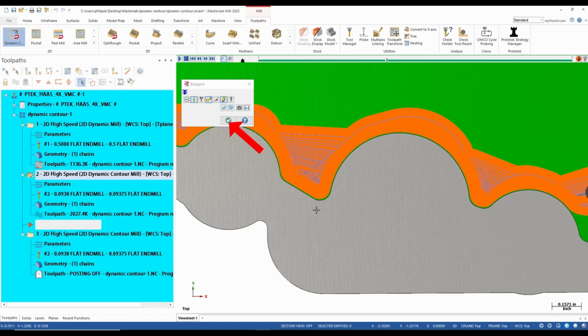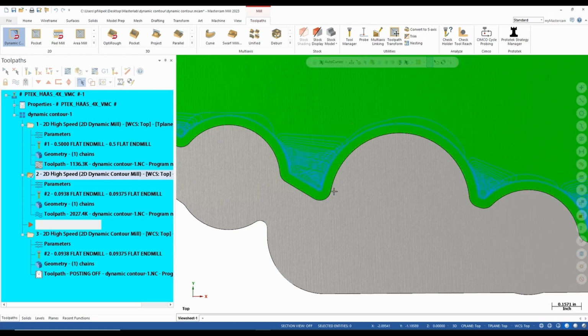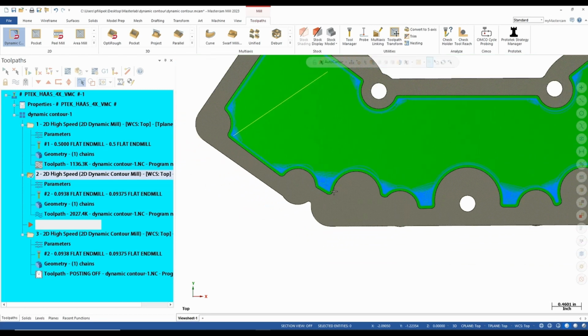So I definitely hope you can go back and start to utilize this tool path in any situations like this where you rough something out, but you've got a little bit more material left over in corners or little areas that a bigger tool couldn't get into. This is a lifesaver for smaller tools, like in this case here, and even bigger tools potentially too, where you want to maintain chip load throughout the cut.